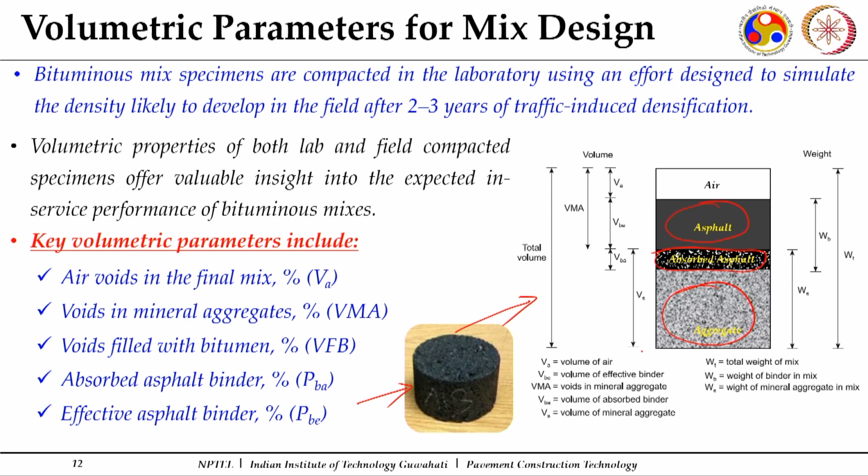What I am mentioning here is Vs, my volume of aggregates, specifically the volume corresponding to the bulk specific gravity, because to a certain extent the binder goes inside it. So, this is my volume corresponding to the bulk specific gravity, or volume of my solids, including the surface voids. Some amount of binder has gone into those surface voids.